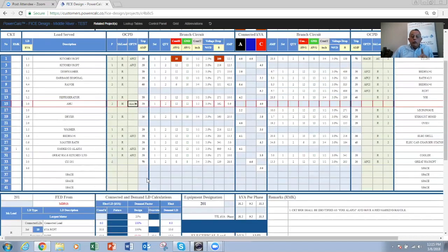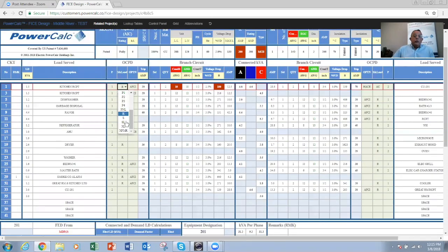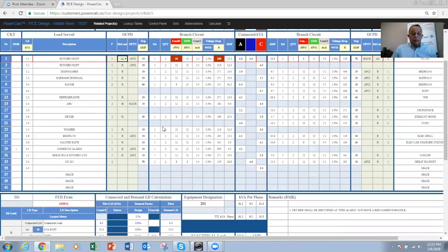And the way you do that, only on residential, you assign the load type to R, which stands for receptacles. But if it's in a commercial building or a hospital or a factory or an office, you're going to assign the appropriate type of load to that particular load, and so forth. Again, because the requirement for the demand calculation is different between a commercial building and office buildings. All the loads other than the air conditioning, that's the only one that you cannot demand under the code for the residential as being lighting and power load.